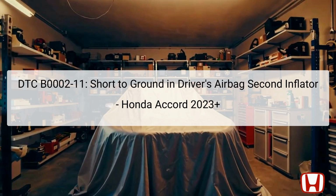The driver's airbag, second inflator, plays a crucial role in the airbag deployment during collisions, ensuring the safety of the vehicle's occupants. Located in the steering wheel, the driver's airbag is connected via several wires, including the cable reel that allows steering movement. If the system detects that the electrical resistance across these wires is lower than expected, it triggers this DTC as a safeguard. Therefore, understanding this fault code is essential for any professional or DIY technician working on the Honda Accord's SRS system.